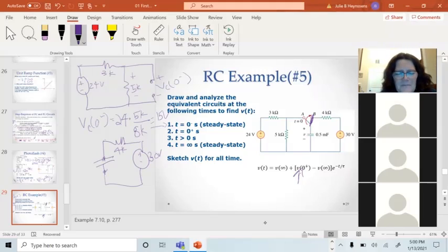Okay. I want to figure out how fast it's going to be charging from that circuit. I know the initial voltage on there is 15 volts. What I do, and this is where I use Thevenin, the only point in my life where I ever liked Thevenin, if I want to find the equivalent resistance that that capacitor sees, what I have to do is deactivate all the sources.